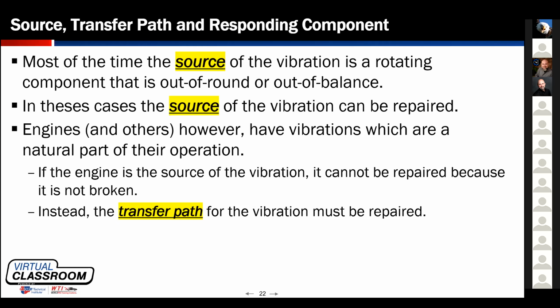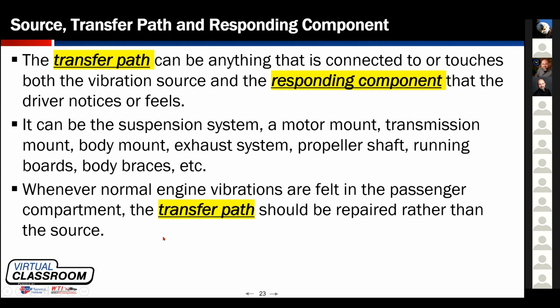Okay? But the thing is, if my engine is the source of my vibration, but I determined that that source is common to that component, or that component is supposed to produce that vibration, then we can't fix the source of the vibration because it does that naturally, which means instead of fixing the source, we now have to fix the transfer path.